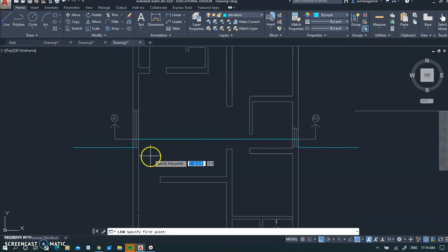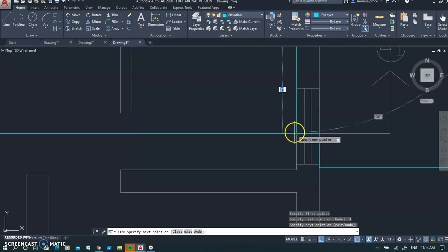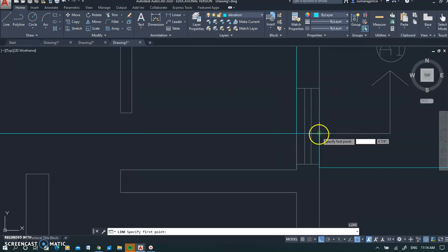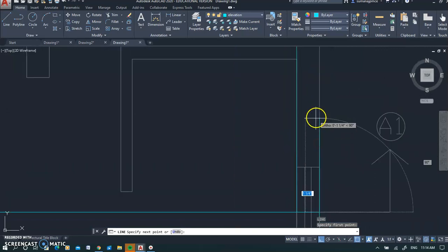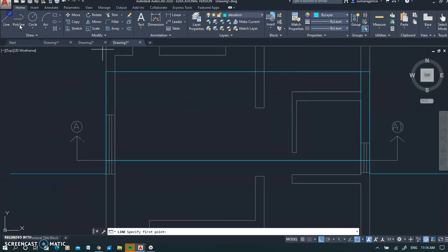Now we know the wall is here. See, I'm working on the section line itself, so there is no risk of projecting lines. I will go up here by 3 meters. You know that the building height is 3 meters. When you do a 2-story building, you'll have to be careful with that. Now I come down here, just zoom in and work every time you do that. And that's the wall line. The walls are cut, okay.